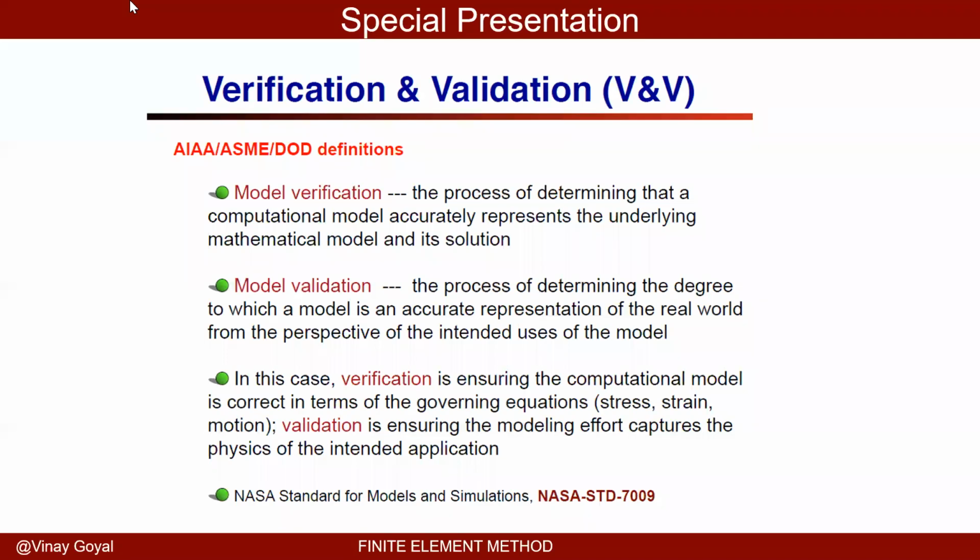And if you put a load on it, it should give the exact displacement that a continuum solution would give you. That means if you have a cantilever with an end load, your finite element solution should give you the end displacement as PL cubed over 3EI, where P is the load, L is the length of the cantilever, and EI is the flexural rigidity.